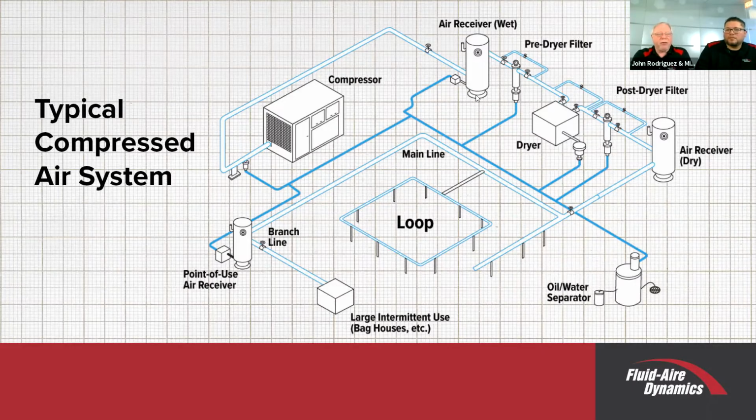The other thing is that if you have any moisture in your line and you run liquid water into a refrigerated dryer, the dryer is designed to take out humidity. If you send liquid water into it, it becomes a water chiller. So you do not want liquid water entering the dryer. It won't do its job. And from the dryer, we drain more moisture out. Again, we have a pre-filter here to protect the dryer from any contaminants. This would be that particular filter. Right, the particulate filter, one of the two that we mentioned earlier, yes.